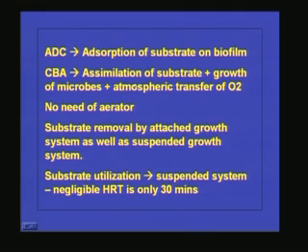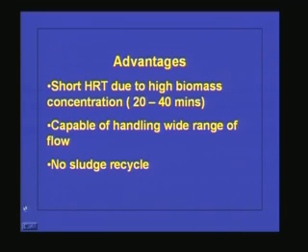Because of this process there is no need for any aeration. Substrate removal by the attached growth system as well as the suspended growth system is taking place, and substrate utilization by the suspended system is negligible because the HRT is only 20 to 30 minutes.